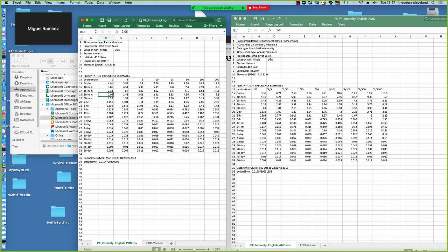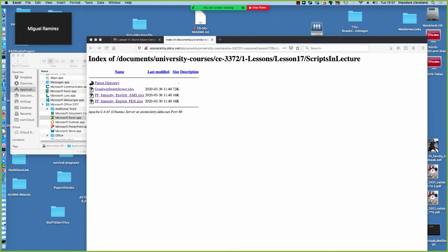But if not, and you have access to both, use partial duration series for the 2-year, 5, and 10, kind of dealer's choice for 25 and 50, and then for 100 and beyond, it doesn't matter. You get the same results. So that's the difference between the two.